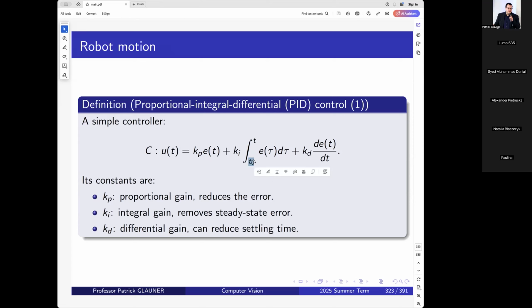You could take all the past errors and sum them up from t0 up to our current t, but maybe there are lots of old errors that are not relevant. And then this integral would also not be bounded, or it would not be fixed because you're starting with t0 and t keeps growing. So the longer this runs, calculating this integral or the sum would become slower and slower.